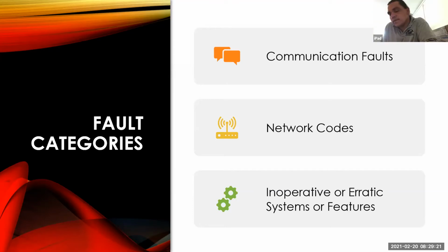Yeah. Okay. All right. You know, a lot of manufacturers have gone to not soldering. Part of the reason is people don't necessarily solder well. Sometimes accessibility, trying to solder upside down underneath the dash isn't fun. But the big thing is what they were finding is because people weren't soldering correctly, they were putting excessive resistance in the circuit with the solder joint and cold joint problems. Cold joint, yeah. So it's not that soldering's bad, it's that people don't do it well and it's hard to do.